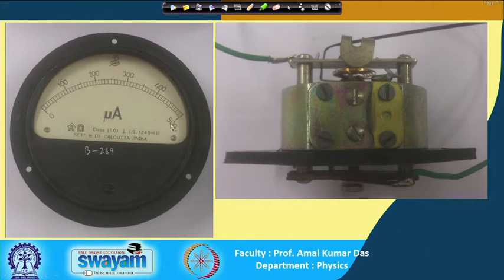Okay. So, here the shunt resistance is connected, but I am not able to see it here, I think it is broken. So, you see again this ammeter is nothing but a galvanometer, but a shunt resistance is connected in parallel. One has to connect it in parallel, but here either it is inside, which I cannot see.